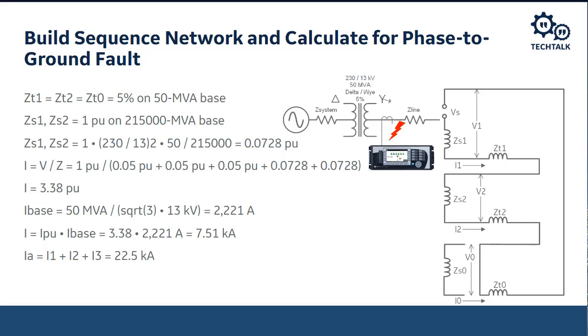this, at the substation bus, oftentimes if you know the system impedance and you're using the system impedance, the phase to ground fault current can be a little bit larger than the three-phase fault current. This is very important if you're doing an arc flash study, or even if you're calculating the fault current for the duty cycle to know the interrupting rating of the circuit breaker. That phase to ground fault current may be just a little bit larger.